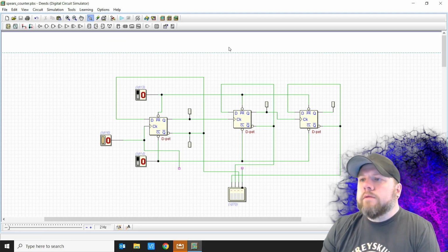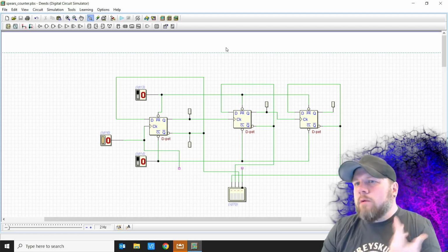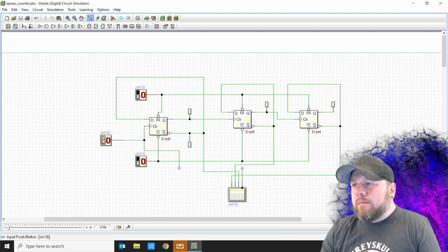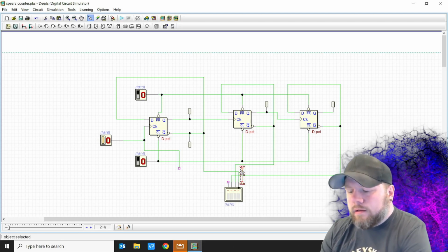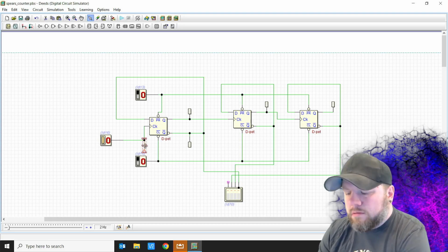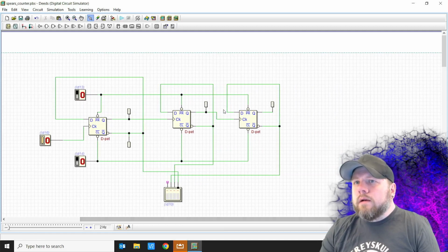All right. So I want a full 4-bit counter, and I'm not going to use my button as part of that. So what we're going to do is we're going to stop it. We're going to move this over 1, right? Go ahead and delete the wires that I had coming from my button. We'll just ignore the clock, right? Since it's not edge triggered, we're getting a little funkiness right there.